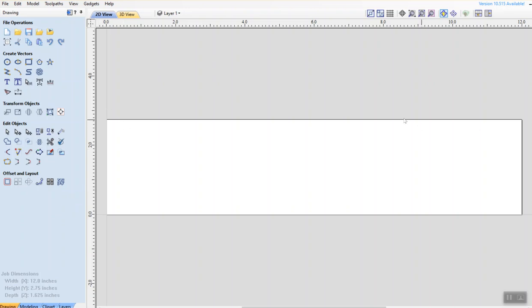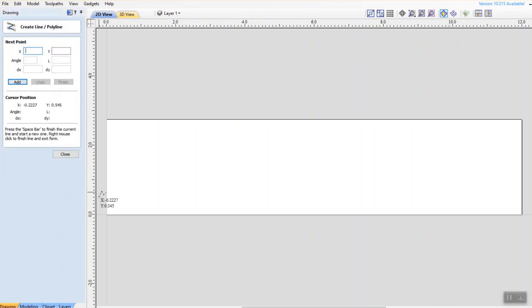Now, this balsa wood is 12 inches by 2.75 inches. So I'm going to draw a center line in the middle, just in case, to accurately locate the hole. As I move my cursor, the computer shows me 1.375, which is half of 2.75 of an inch. So click on it, you go inside 1/8 of an inch, and I'm going to go to 2.5 inches.